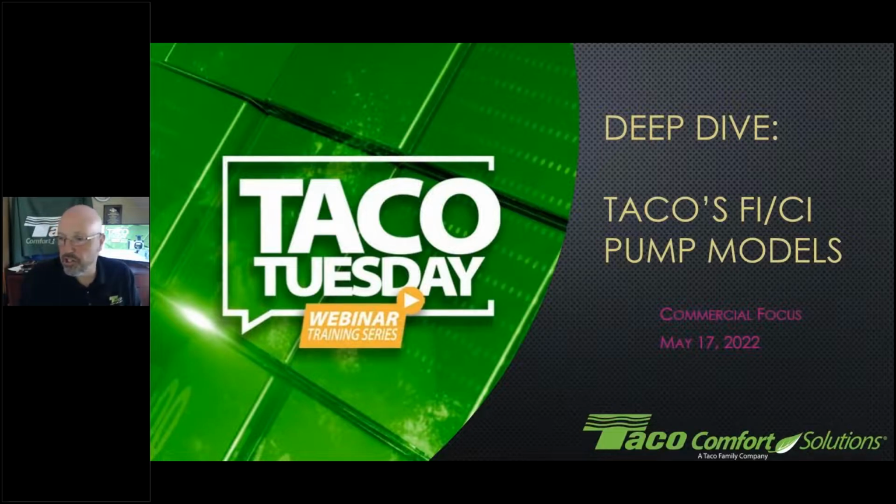So I just saw a question drop in from Vincent, and he was asking about SureStart on all of the ECM circulators, our smaller circs, not up to the VR versions. Right now, our ECM circulator lineup goes up to, I believe, 65 feet of head, 320 gallons a minute. Some of the big pumps do not have SureStart built in. Our smaller ones do. From the 18 down, and Rick, maybe you can correct me, I'm not sure on the 26 and 34 models, if we have SureStart built into those. Yeah, up to 170 watts. Okay, excellent. 170 watts has got SureStart built in there. Excellent, excellent.